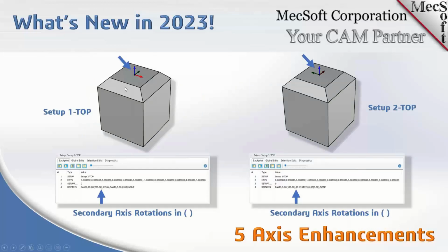Now here, the two 5-axis enhancements I just mentioned. On the left, if you look down here at the arrow, we're outputting the alternate way of getting to that orientation. Previously, we only output the one angle, and now we can output the alternate angles as well. And you can use these, primarily you would probably use these in post-processing or our programmable post.